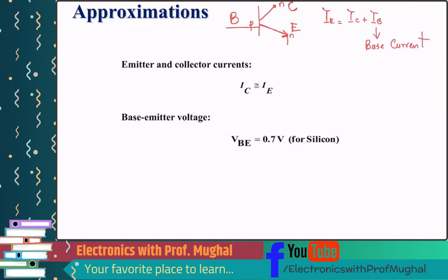So you have current flowing into the base, which we refer to as IB. Then you have this current IC, the collector current, and these two currents flow into the emitter terminal, IE. So if you apply KCL, if you consider it as a node, you have IC coming in here, you have IB coming in here, they combine and give us this equation, correct?